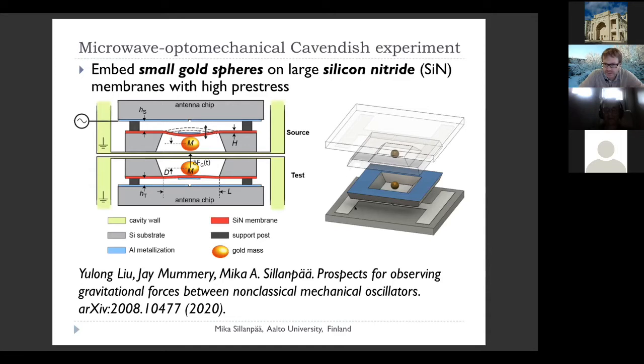And this needs 4 chips. It's not a very complicated structure. It would be very tempting to just press all of these 4 chips together. It would be very simple to make, unfortunately not possible, because there would be huge cross-coupling just mechanically through these chips. So in practice, they have to be physically separated.